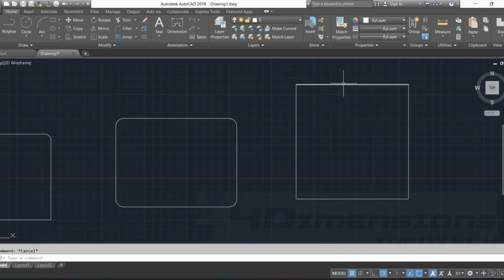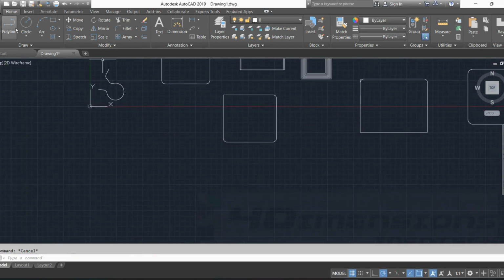But if I go for this option, which is not made by the polyline, say F enter, select polyline, then radius value, say 1200 only as the radius value. And if I click on this rectangle now, it is not been filleted here. It is because this is not a polyline, and you can see at the cursor it is asking for selecting the 2D polyline only. So as this object is not made by the polyline, it is not been filleted here. So from that we can understand that only polyline objects are required here so as to make fillet with polyline.